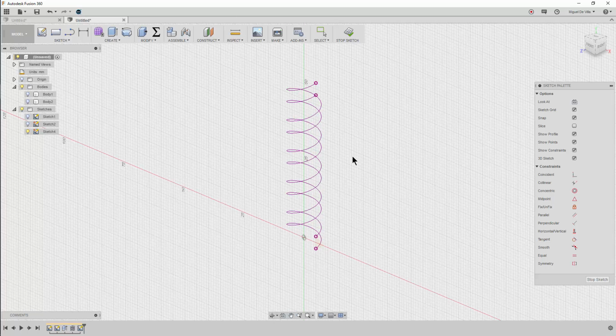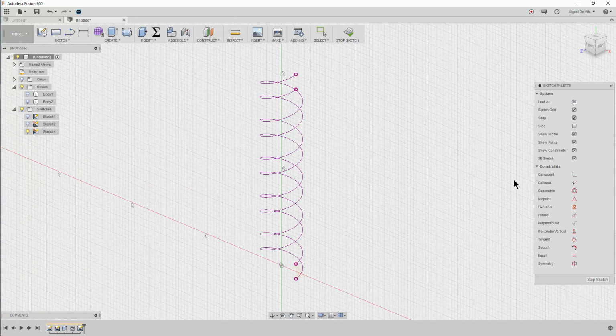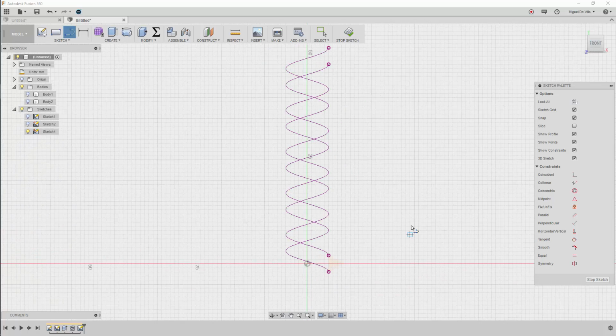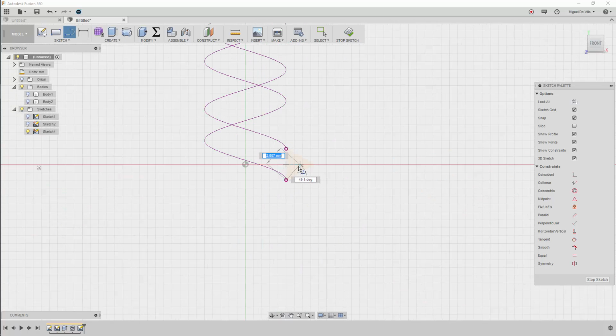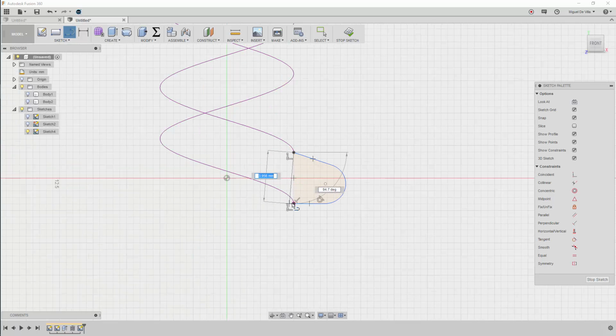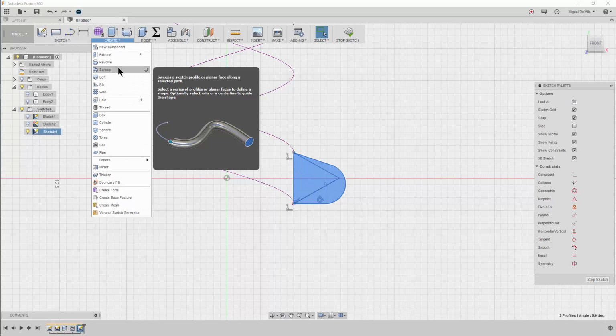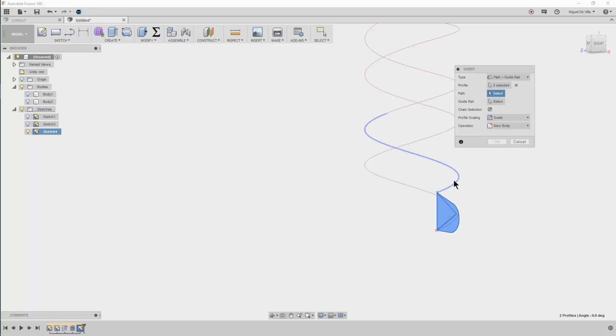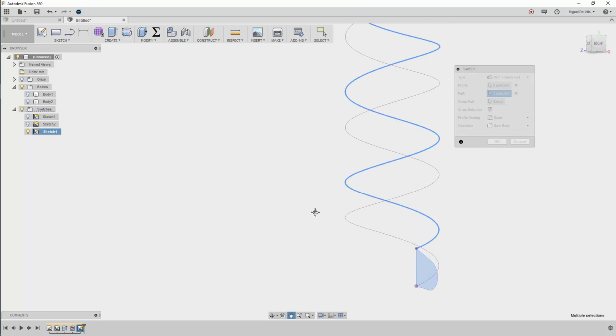You have to be thinking, hold on, why do we need 2? Well, the reason I'm about to show you: we need 1 to be our sketch path and 1 to be our guide rail. Because if we don't, and let's start out by drawing a very primitive custom thread profile here, this weird little oval, and we are going to sweep it along just one of these pathways, like so. I'm going to make a new body too. Oh, change that to single path.